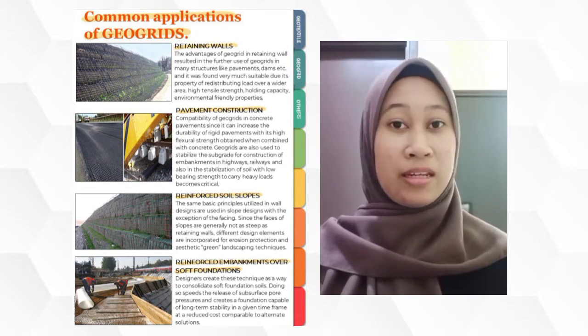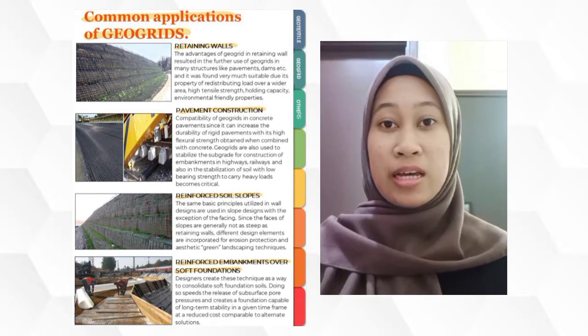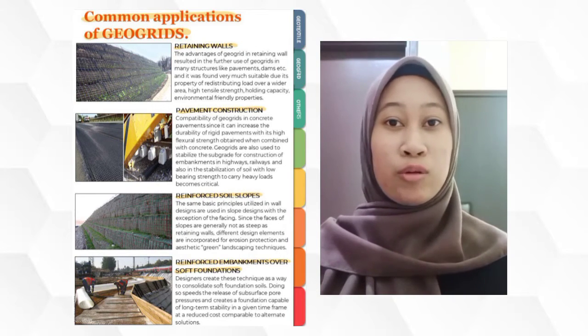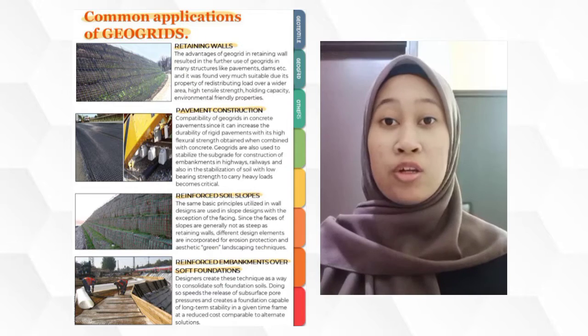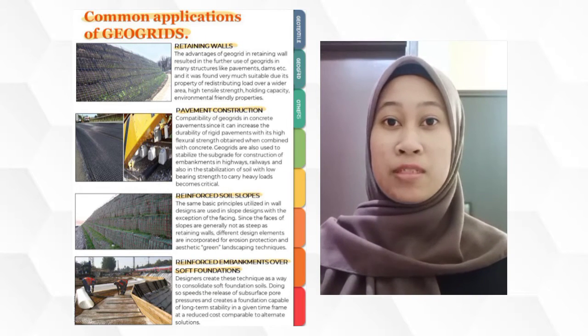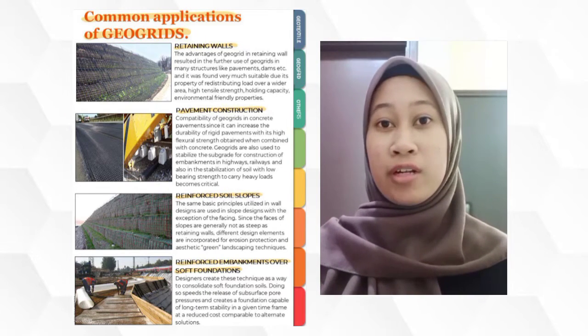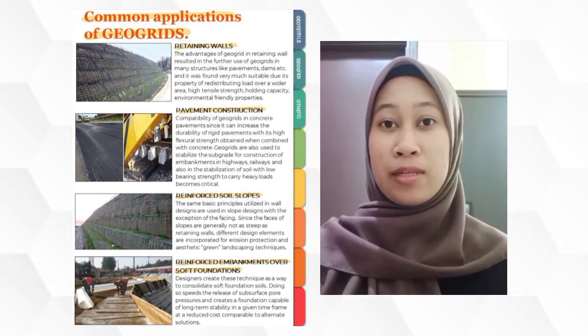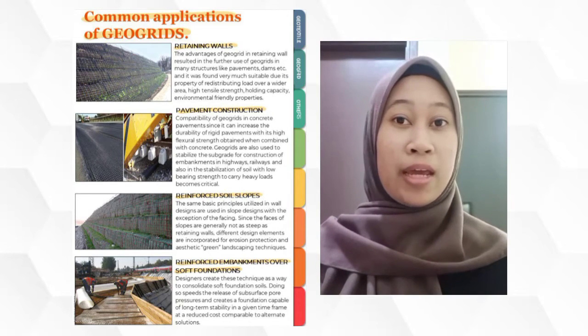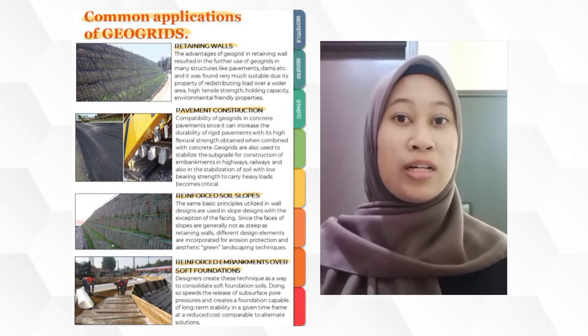And last but not least is reinforced embankments over soft foundations. Designers create this technique as a way to consolidate soft foundation soils. Doing so speeds the release of subsurface pore pressure and creates a foundation capable of long-term stability in a given time frame at a reduced cost comparable to alternate solutions.